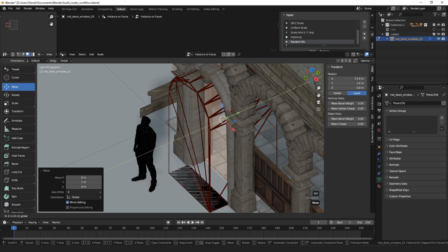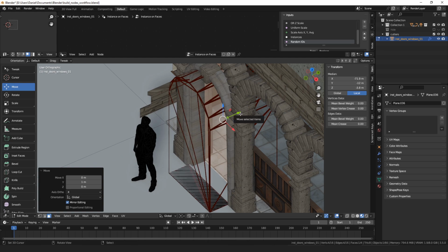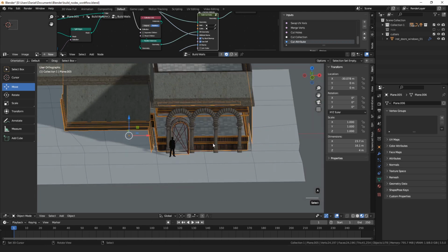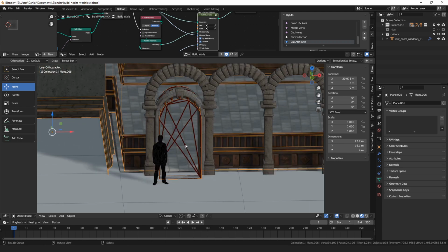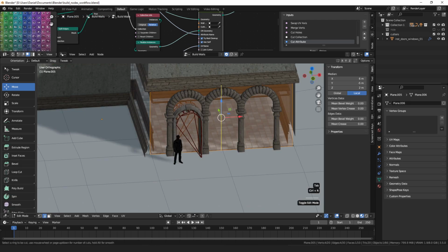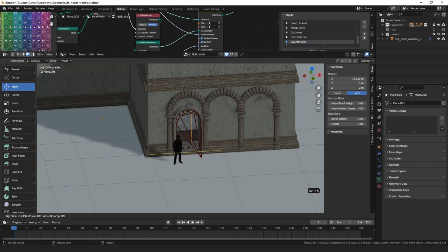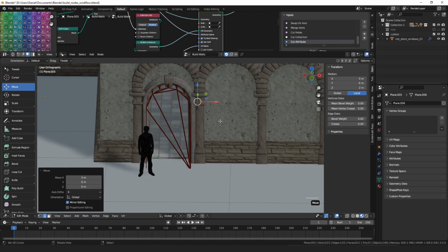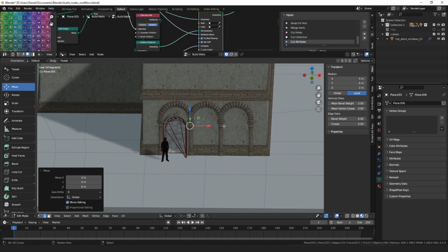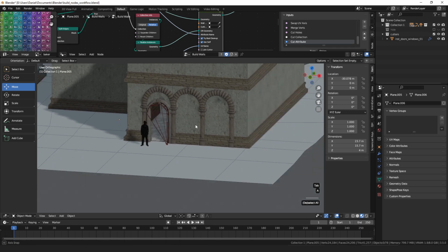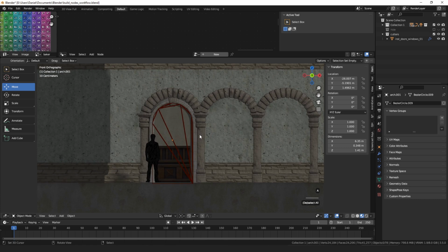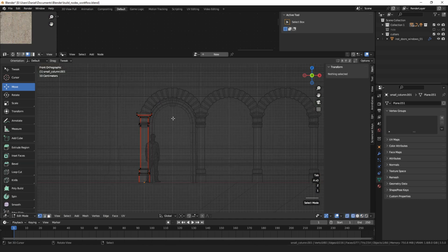Okay, and unfortunately this happens sometimes. Blender and Booleans can be finicky. For now, what I found that works pretty good is usually just adding an extra loop cut to divide your wall up. It seems to mostly have trouble if there's not enough geometry. So adding an extra loop will kind of fix the hole cutting. And I don't really like this. I guess that looks okay.